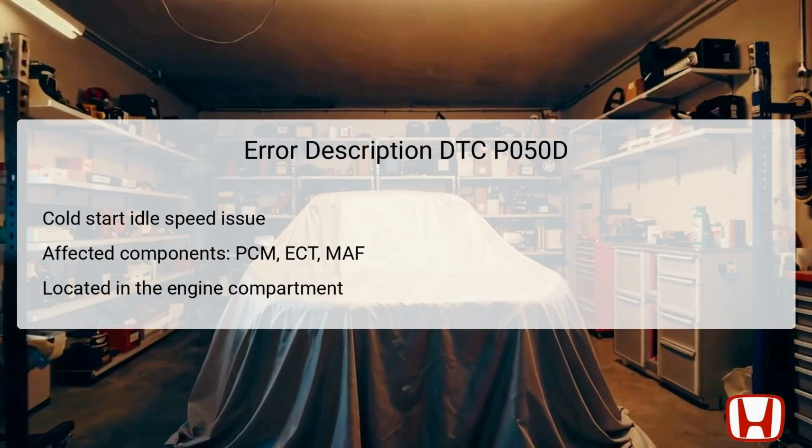The DTC P050D refers to a cold start idle speed problem. The primary components affected include the Powertrain Control Module, PCM, which oversees the vehicle's engine management, and the engine coolant temperature, ECT sensor, which informs the PCM about the engine temperature. Additionally, the mass airflow, MAF sensor, plays a role in measuring the amount of air entering the engine, which is crucial for proper fuel-air mixture.